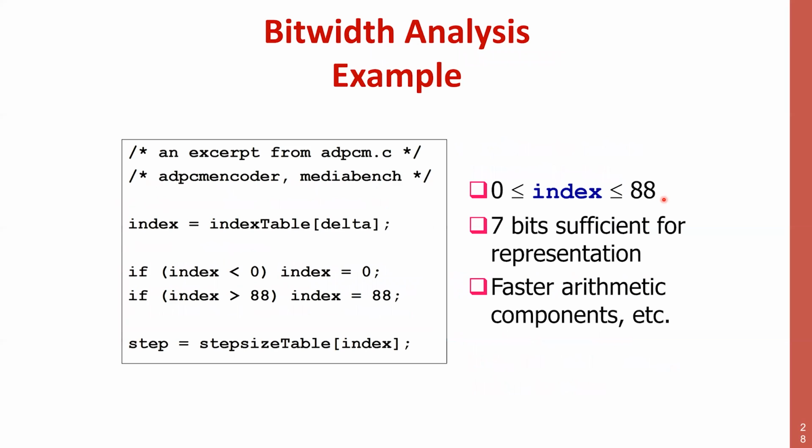So it's another advantage of doing hardware. In software, if I have a 32-bit multiplier and it takes one cycle, that's it. If I need to multiply 3 bits by 3 bits, it takes one cycle, because that's the multiplier I have, and it doesn't even make any sense that I put a smaller multiplier in my architecture, because in any case it will take one cycle. Now, if I look at my code and I discover that something needs a smaller number of bits, right?